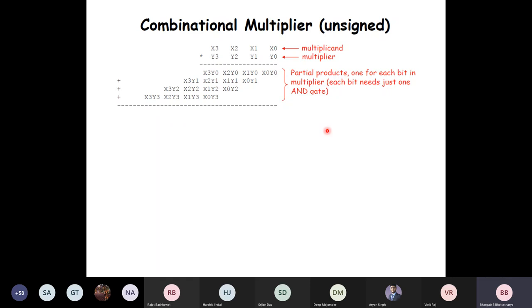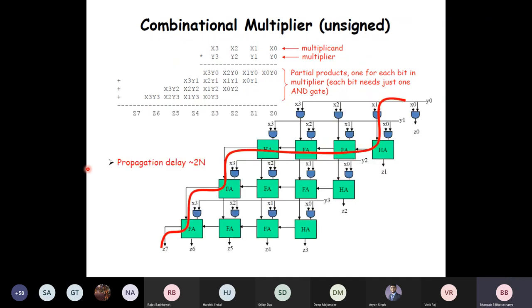So what could be the overall design of this? Simple design of a multiplier. For the time being, forget about the cost and delay and so on. Just think of you have an array of AND gates, and then you have an array of full adder blocks. They are adding these numbers along the columns and propagating the carry to the left. Okay, so let me show you the overall diagram, and then you would be able to see that it is obvious.